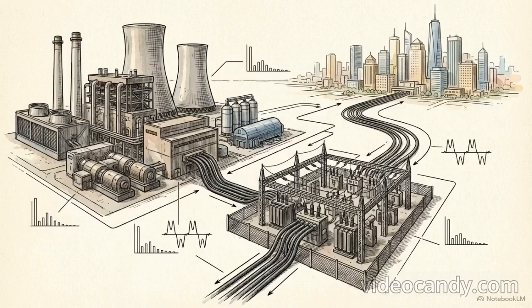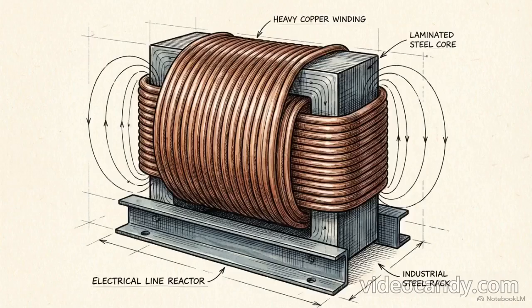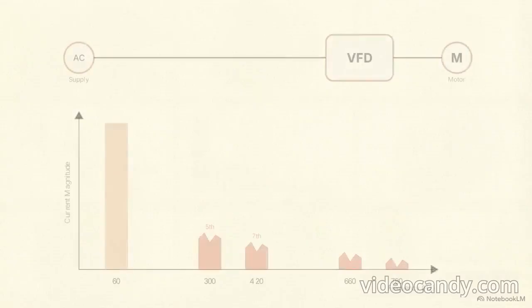on the upstream transformer. The strictness of the TDD limits applied to a facility depends on the grid's short-circuit ratio. A stiffer power supply with a high short-circuit ratio relative to the maximum load can safely absorb more harmonic current without suffering severe voltage distortion. By enforcing TDD, utilities bypass the mathematical noise of fluctuating daily power consumption and regulate the exact volume of high-frequency pollution entering their infrastructure.